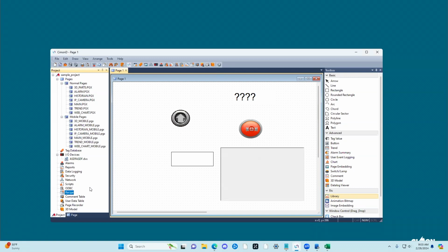Or you did a physical calibration externally from the software, and you want to retain those values in the software for later use. So you calibrate your machine, extract those values into the SCADA software. You create a recipe or an ingredient list of that, and then just store it for later use. So that would be the beauty of recipe. It stores permutations of your project for you.